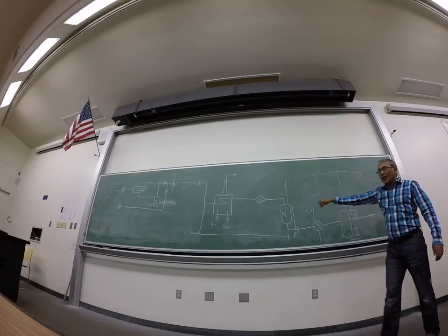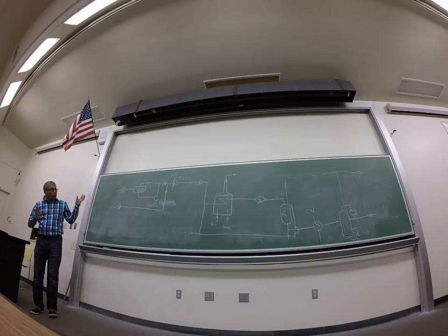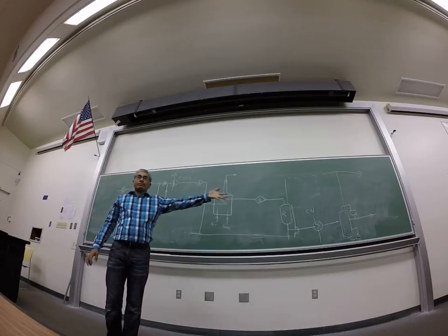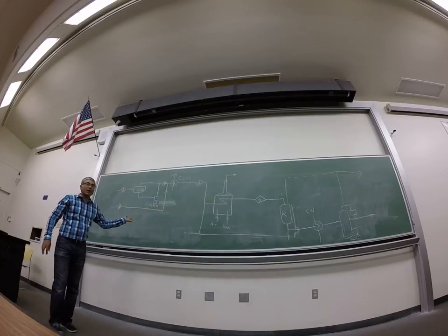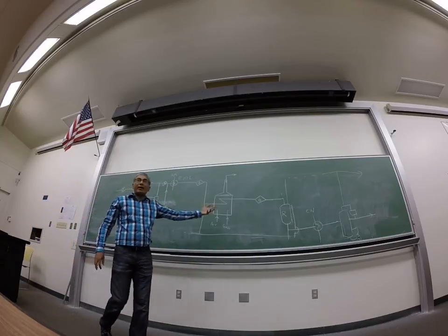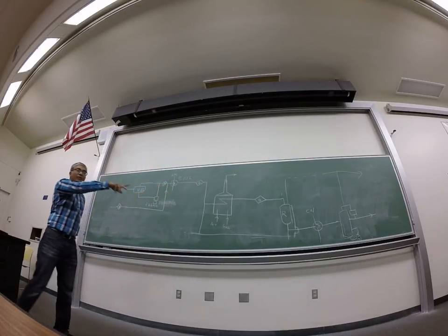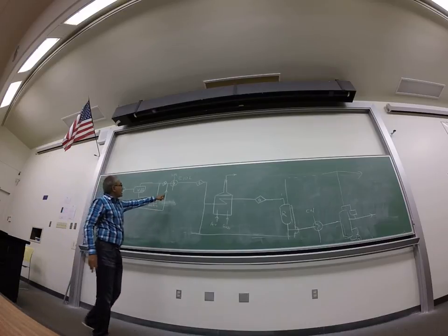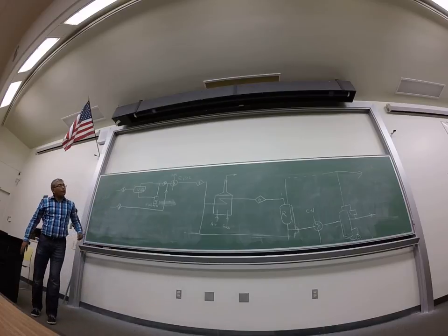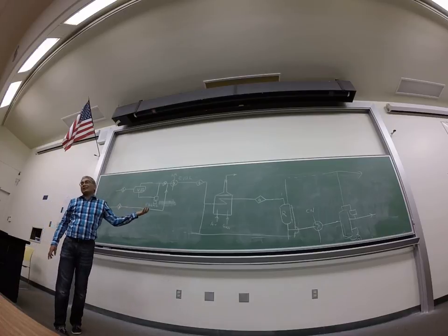Okay, so this is not actually exactly complete. I'll upload this and you can see it. But the important thing is, what are the important things? The important things are now we're actually putting every equipment in, and what type of equipment it is. Okay? It's a heat exchanger, we're putting a heat exchanger, it's just a vessel. So really now you have a better idea of what every equipment is. We're putting in numbers for every stream, right? Also we're indicating all the utilities, right? And then of course you have to put in a few more details like all the mass balances. And once you put in all the mass balances, that's essentially a process flow diagram.